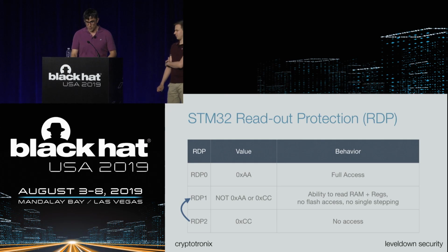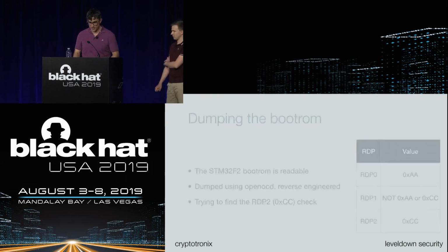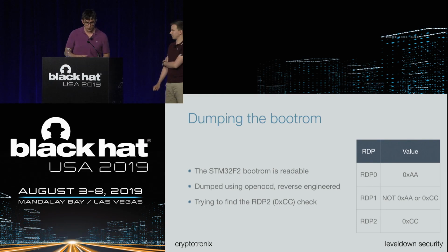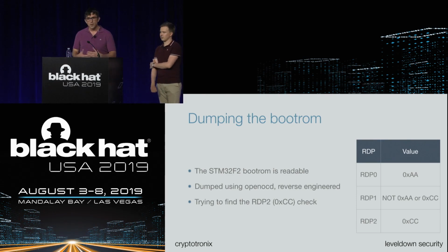And so the way to do this is basically to look at the bootloader. So we were able to dump the Bootrom, and one of the things we were interested in, so we had the hypothesis, does RDP only get read on the Bootrom?